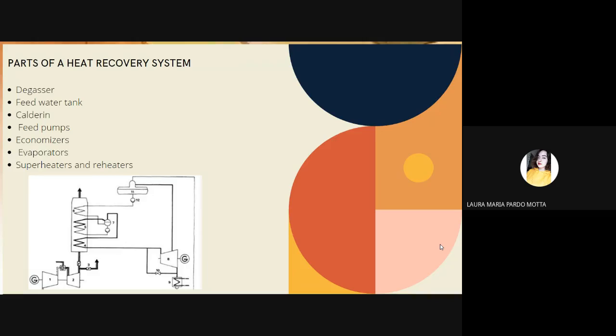And superheaters and reheaters are the exchangers that are located in the part closest to the entrance of the gas from the combustion in the gas turbine. The steam that comes out is ready to be sent to a steam turbine. This steam must be as pure as possible, and free of drops of water that will deteriorate our turbine.